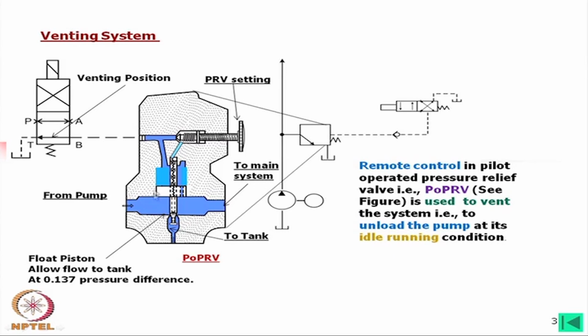However, another important thing is that whatever the pressure on this side, that will try to pull this one, because if you think of the load balance, this side load and this side load form a differential load which balances the piston. In the normal case, when there is no flow, there is equal pressure. There will be pressure from this side, and to balance this there is a hole, and the other side has the same pressure.